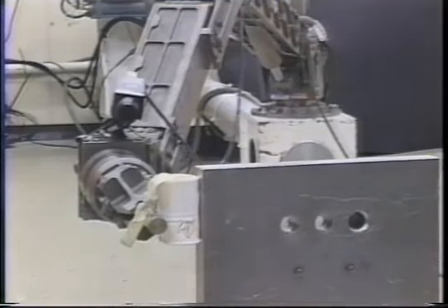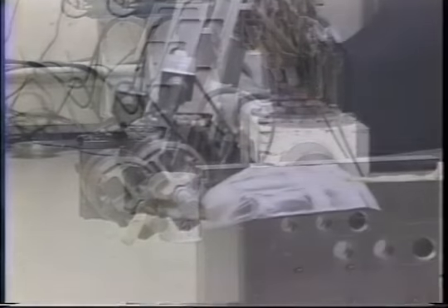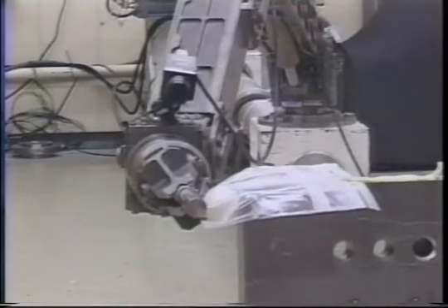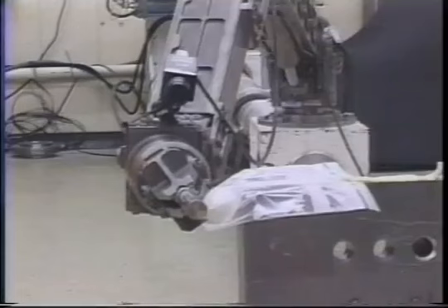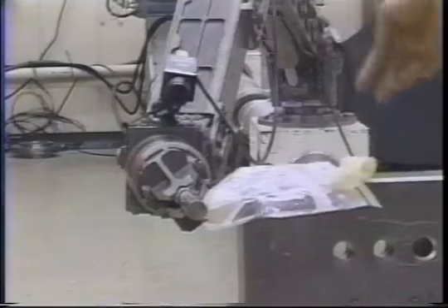Holding a cup against a wall is a relatively simple task since the cup is very flexible. This time we experimented with something not so compliant, a fragile egg. Again, the manipulator is force-controlled in the horizontal direction. The manipulator contacts the egg and regulates the holding force to be about 1.5 pounds. Any overshoot or chatter of the force control will break the egg.